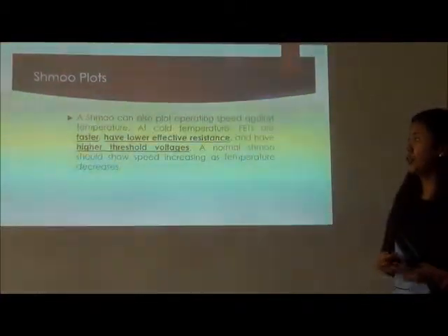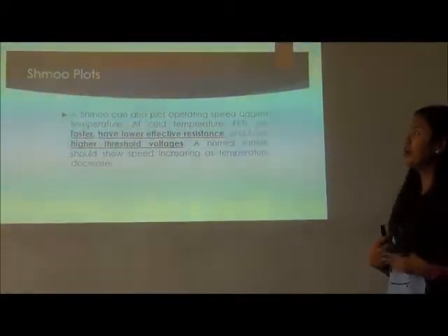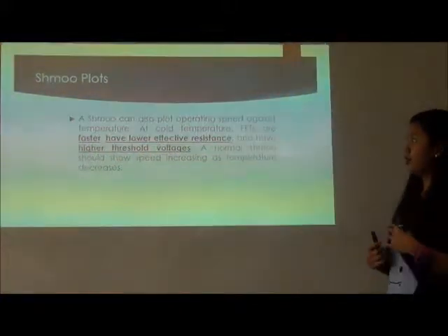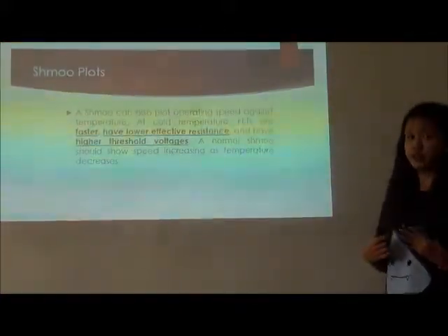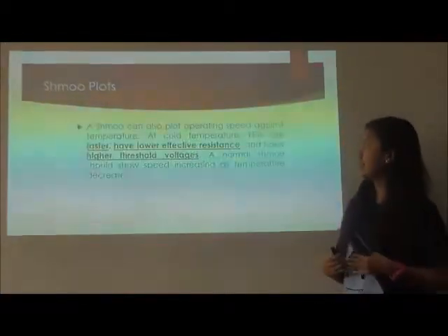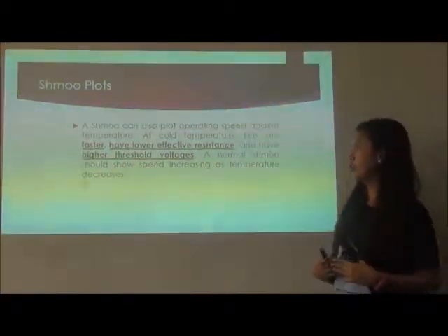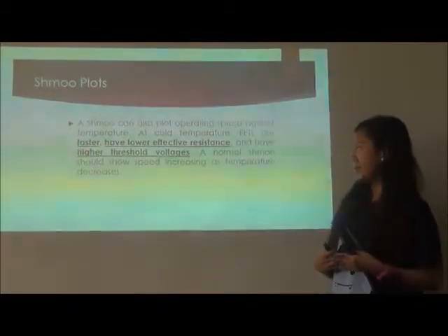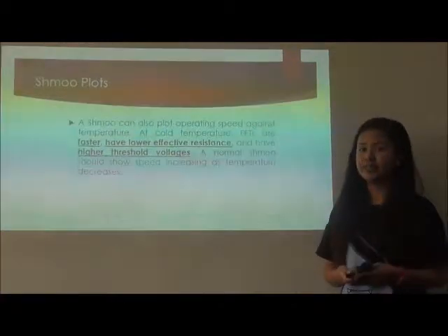A Shmoo plot can also plot operating speed against temperature. At cold temperature, FETs are faster, have lower effective resistance, and have higher threshold voltages. A normal Shmoo plot should show speed increasing as temperature decreases.